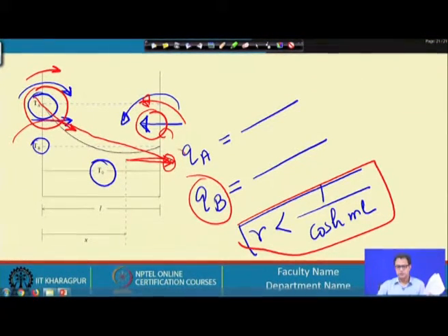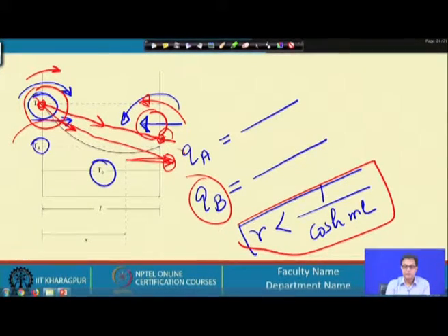transverse heat conduction. This has to be either taken care of separately, or we have to define a fin efficiency to take care of this bypass heat transfer. This is often also called bypass heat transfer, because the heat is as if bypassing from one plate to the other and bypassing the fluid. So, as if directly this heat QA is going from the fluid to the other separating plate.